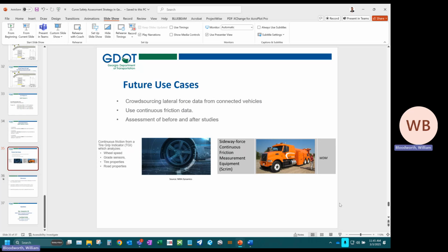I didn't see a lot touched on in the presentation on that, so I'm curious if that's something you wait on, or if it's still very much a tool to use in the future. That's an interesting question, because I think of roadway departures from something like rumble strips and rumble stripes as different from curves. Those are more meant for falling asleep and distracted driving. Honestly, on sharp curves, they are not a proven safety countermeasure. Even for center line rumble strips, there are studies showing increases in crashes from them. I'm not sure I believe those studies, though. They're not proven, they're not very high star rating CMFs, but